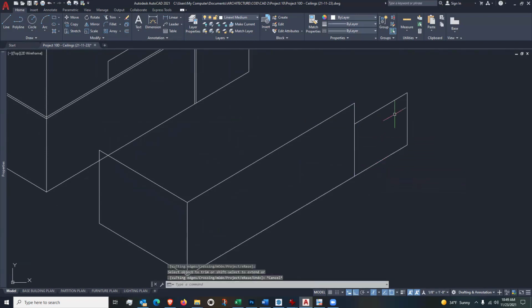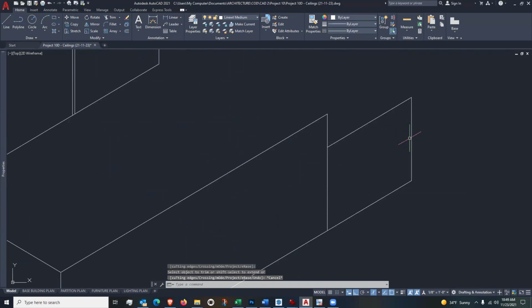That down. Now I've got a little leg here, and that is 1 inch, and then I have a work surface here, and that is 1 inch. So normally I would like to offset these, but I can't. So I need to copy. So I will copy this one over 1 inch, and I will copy this one down 1 inch. And then I'll just clean this up by filleting.